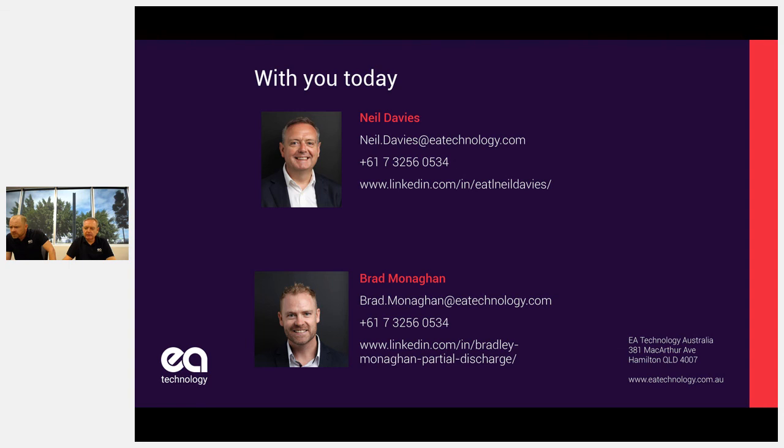All right, we had a question about the histograms. The histogram tab on the UltraTEV Plus, we don't use that hugely amount, really. You're going to get the same information about histograms as you do on the PRPD. So what the histogram really is there to show you is how many clusters, how many different sources of PD that we've got. So it's almost used in conjunction with the PRPD. It also allows you to see the number of pulses per cycle associated with the different clustering as well. So we do use it when we've got a very complicated PRPD pattern.